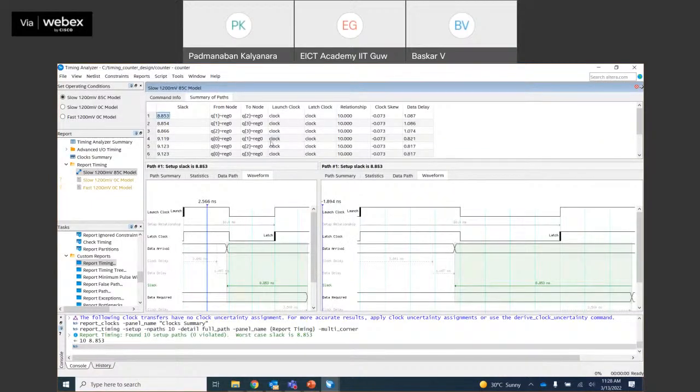Now we can see all the three registers. Interconnect delay is your net delay, right? How you connect it, and then you have the logic delay. Every flip-flop will have three delays. You will have T clock to Q, which is your transition delay, followed by setup time and hold time. And every gate or lookup table will have a combo delay. That is called your cell delay. You will also have the interconnect delay, which is the net delay.